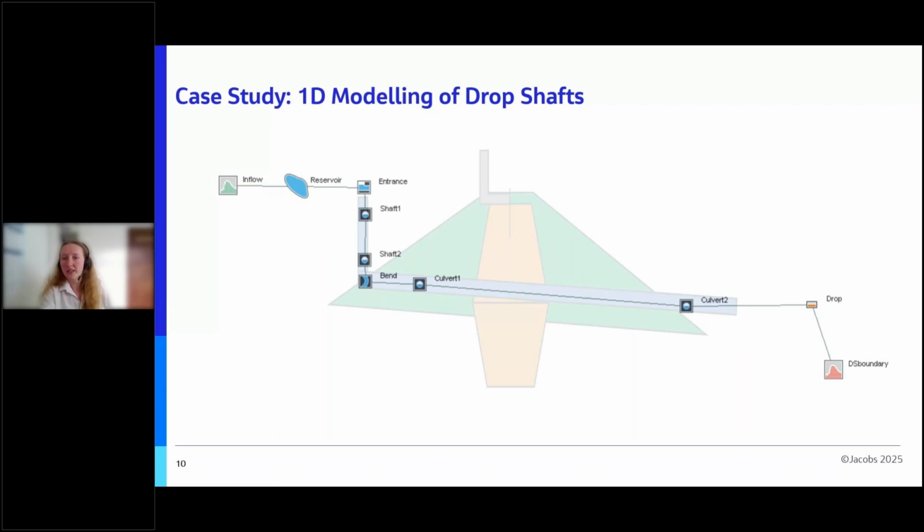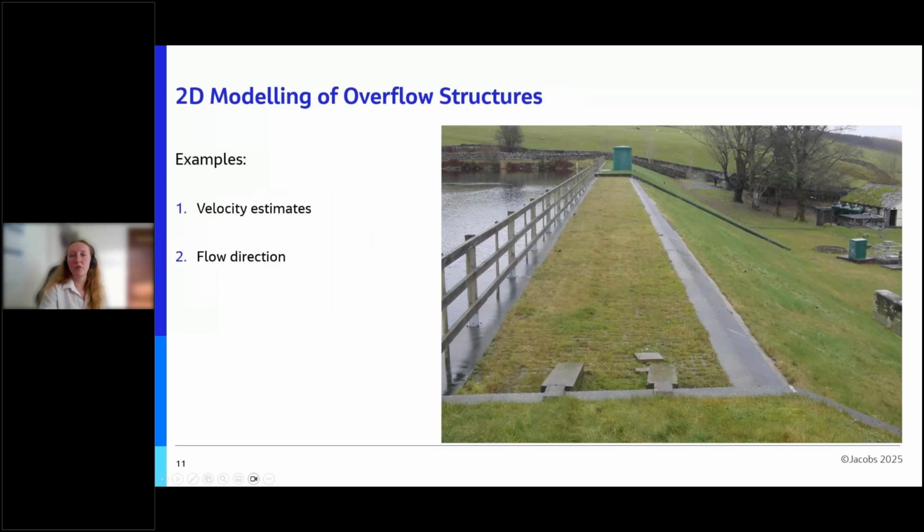The best way to transition from high ground to low ground is with a Flood Modeler spill unit representing the bottom half of the culvert cross section, which is then connected to a freely discharging head time unit. There are cases where you may want to represent your reservoir structures in FM2D, for example, to obtain velocity estimates of flows overtopping the dam.